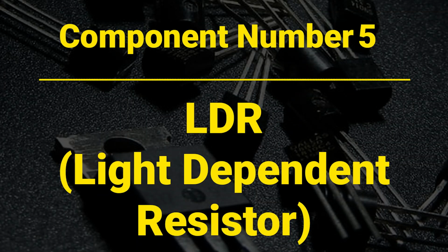Potentiometers are variable resistors that work by mechanical changes the user makes to the shaft, but not all variable resistors are mechanical. Many of them vary in resistance based on environmental parameters like ambient light, temperature, or other factors. I'm going to start with one of the most common, component number 5, LDR or light dependent resistors. This component you see here is an LDR or light dependent resistor, which is a variable resistor that changes resistance based on ambient light. The resistance between its 2 pins usually decreases as the ambient light increases.